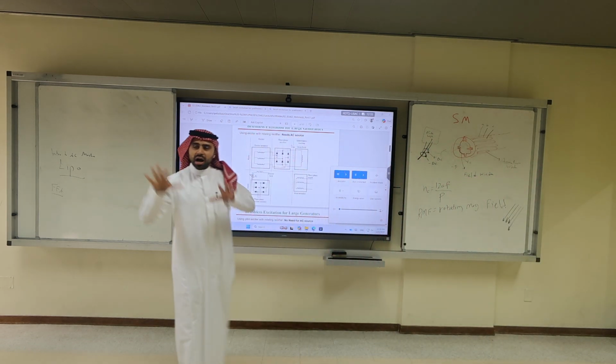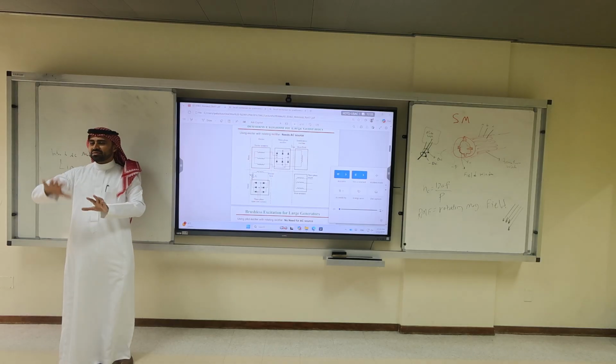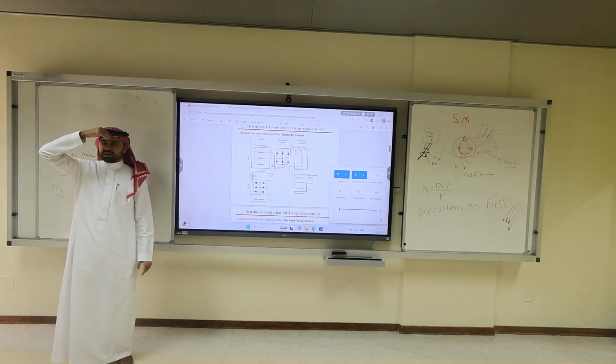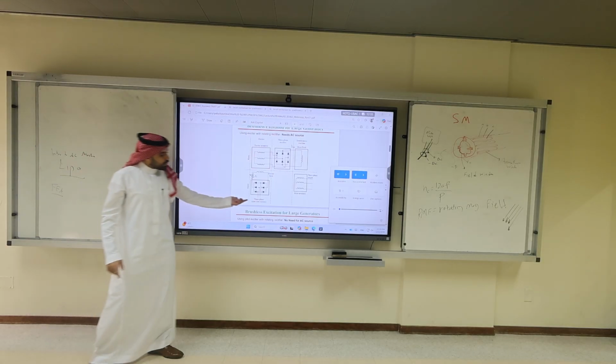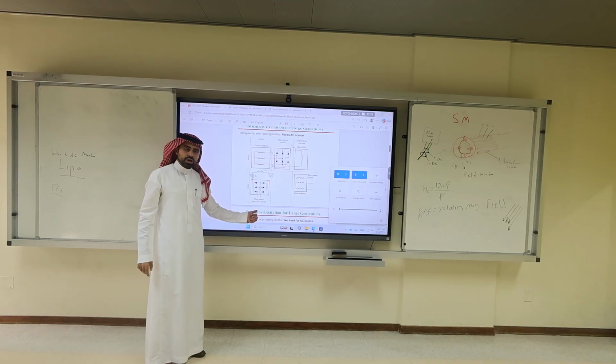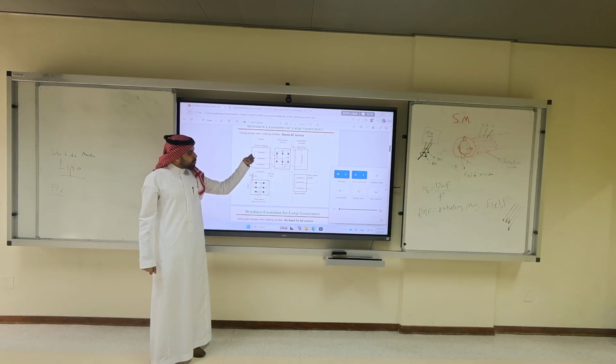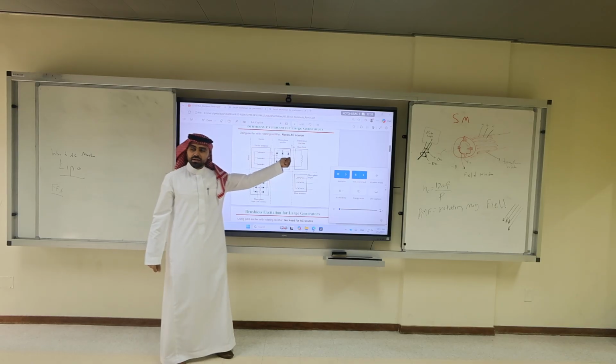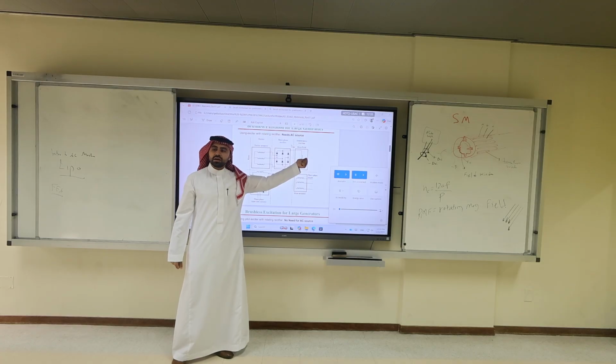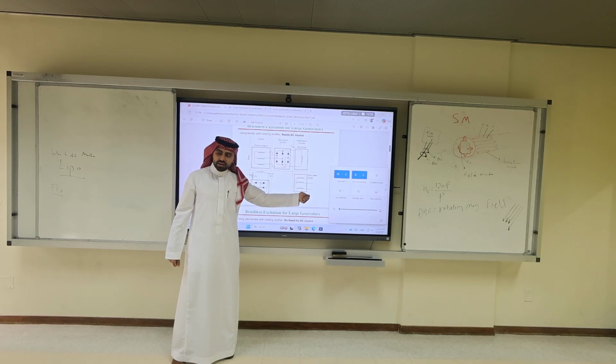We're not going to go into how they do it. Again, this is the winding course. But the concept here is you apply small 3-phase, you rectify it, on the rotor you generate another 3-phase, you rectify it, now you have the DC in the rotor. Because it spins, it supplies what? The 3-phase output.